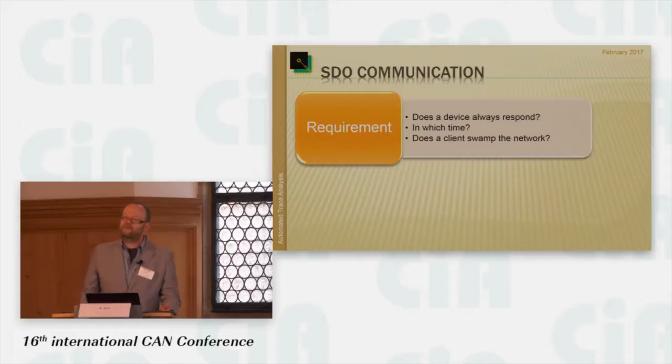Now, that really was helpful in quite a few cases we looked at, because we found out that some of the devices we had on networks did, in some cases, have a good boot up time, in some cases a bad boot up time. Because, for example, CiA 447 specifies that the boot up time has to be within 300-ish or so milliseconds.